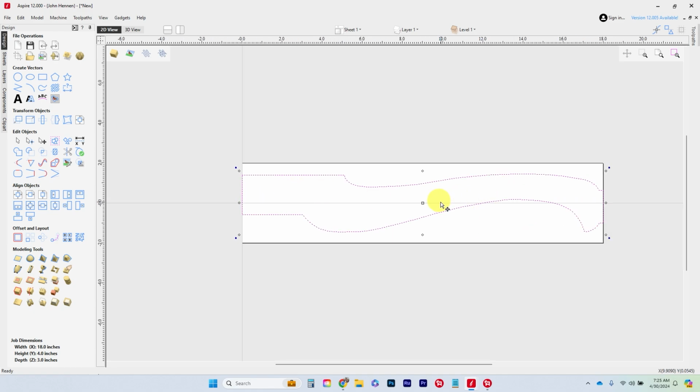We're going to go ahead and start building our cross sections for our 2-rail sweep. I'm going to go into node mode. I'm going to delete this top section and delete this bottom section. That's going to give us now 2 rails, this one here and this one here. We want to make sure our start points are on the front, so P. You hit N right here, you can see that that's our start point. Rails going from left to right. And click on this one. Start points here, rails going from left to right. So those are important things.